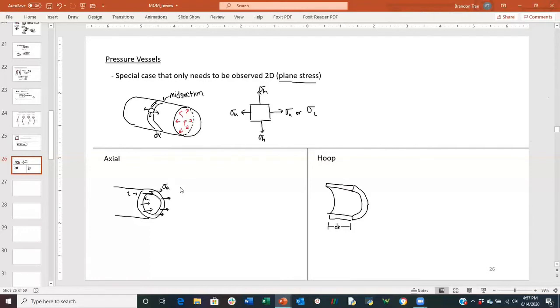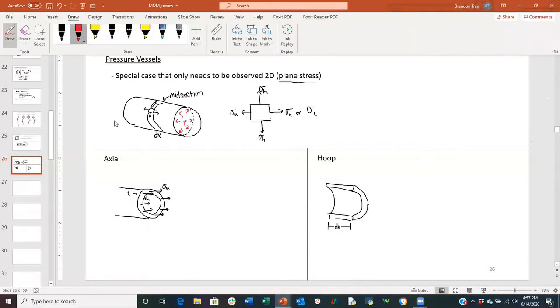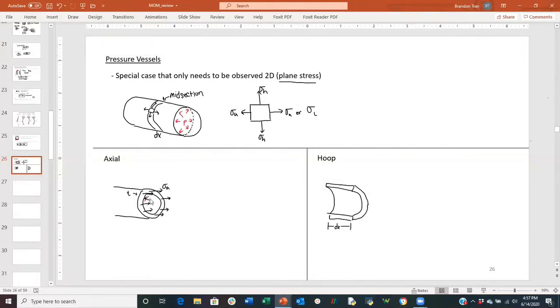The pressure can be modeled as follows. Essentially, the pressure acts on the face plus the thickness of the internal pressure vessel here. We consider the active pressure all the way to the back wall and superimpose that onto this face, so we have basically a pressure P that acts on a circular plate.